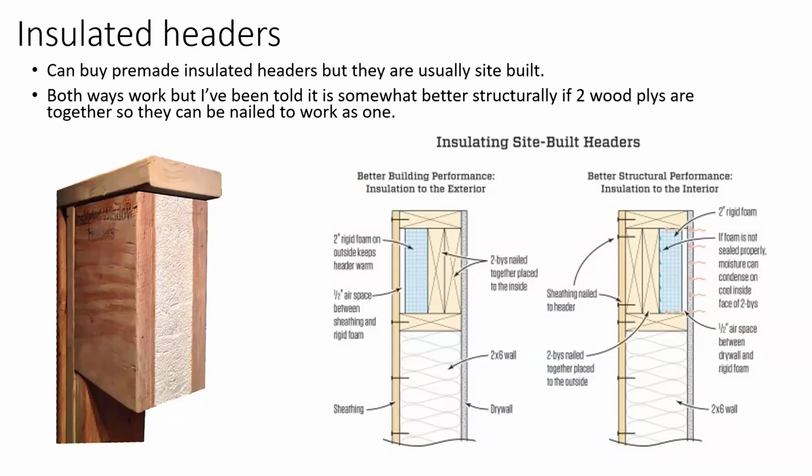I don't really know what the right way is as far as nailing the plies together. And again, the videos I've been telling us about advanced framing do one ply headers. Again, in the real world where I worked all the time, we never did a one ply header. We always did a doubled up header. You guys are nodding your heads. Traditionally, you always do a double ply header.